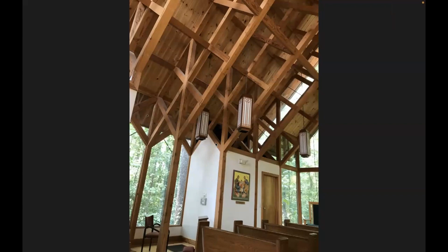Yeah, all right. I would just say this isn't quite a structural analysis comment, but we put these whole wall bents together on the ground, laying flat, and then picked them up with a double hoist crane. So you could basically lift it horizontally and then rotate it in the air with the two hoists, two different cables. And then we had to thread it down through between the trees and then turn it 90 degrees. But the whole time, once you got vertical, it was so stable. Of course, it was a little dicey going from horizontal to vertical.